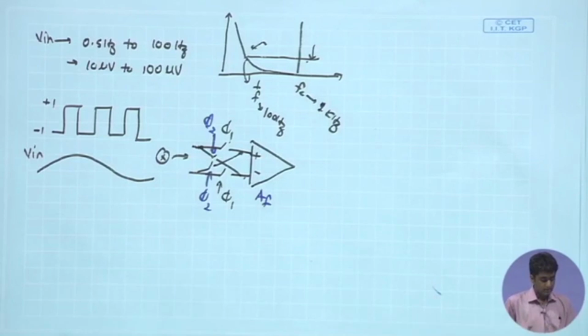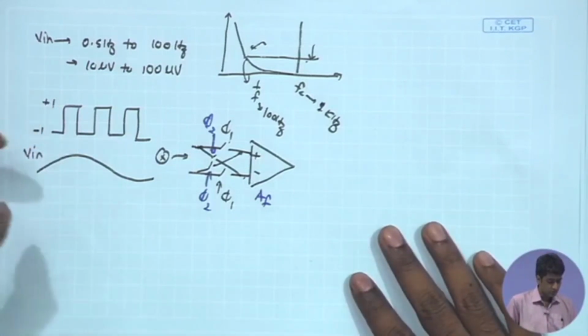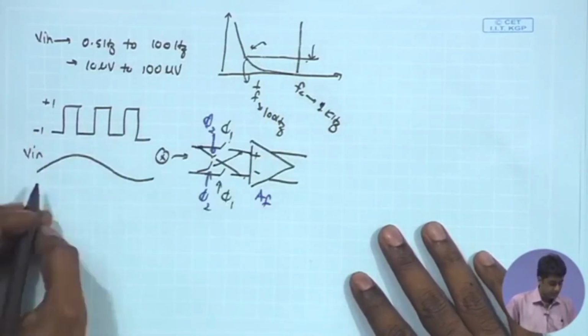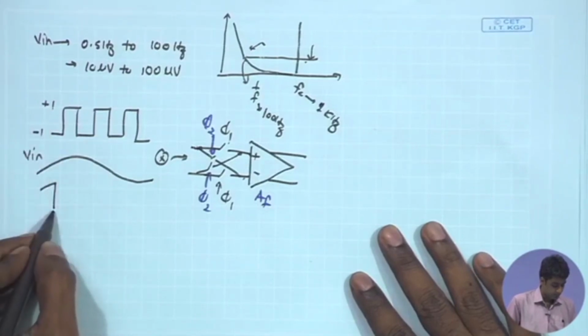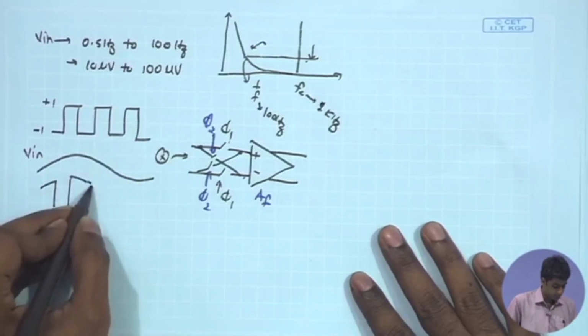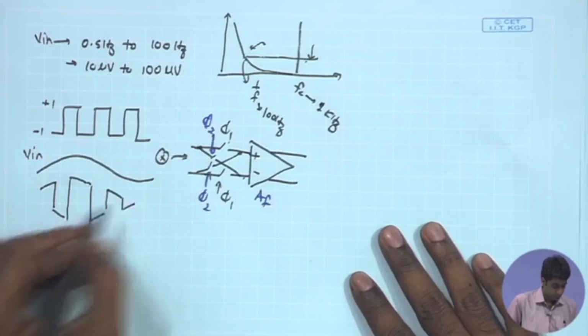And ideally, of course, that would mean that the output signal, if I look at the fully differential output V out plus minus V out minus, will be just getting chopped accordingly. So, you will have the overall amplifier signal getting chopped. So, this is what we expect.